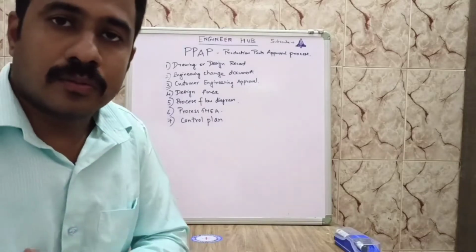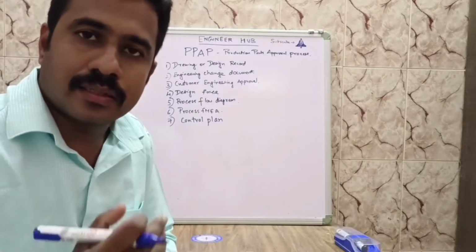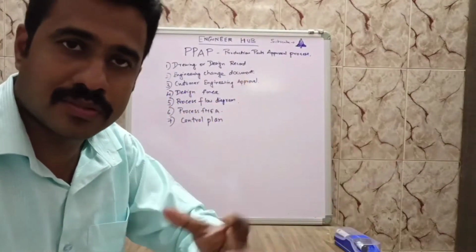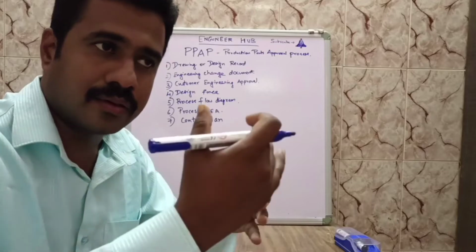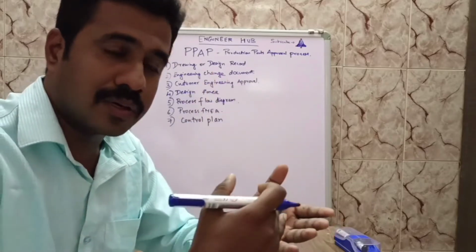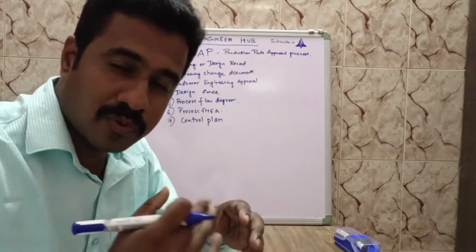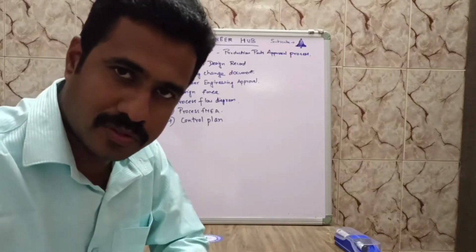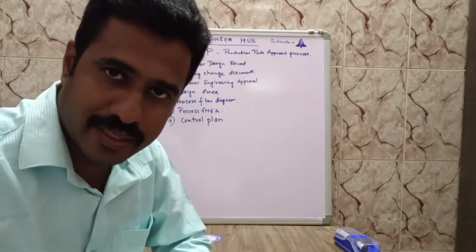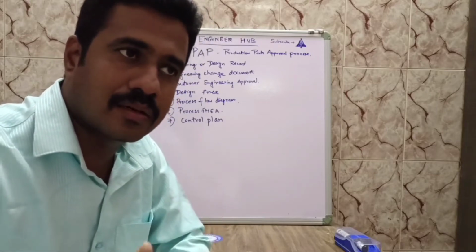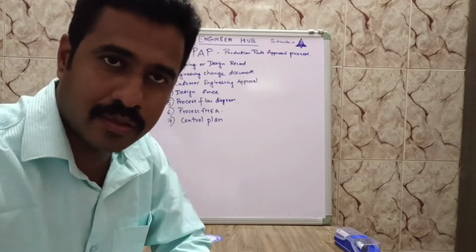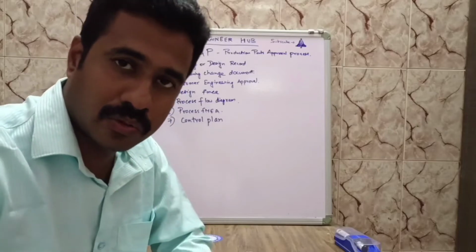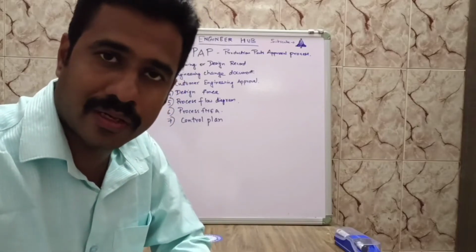Okay. So what is the control plan, basically? I have explained that the process flow diagram is the process. If you're making a component, you have the processes involved and the failure modes involved. Then, if there are failure modes involved in making a process, what is the control to control those failure modes? Suppose there is a dimension variation, or suppose there is no checkpoint for the raw material. So what is the control for checking the raw material, and how do you control the dimension variation of a product?